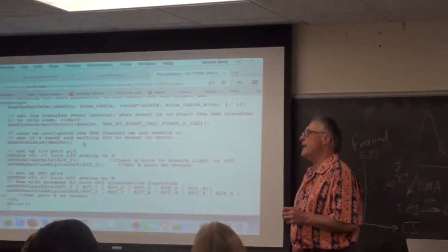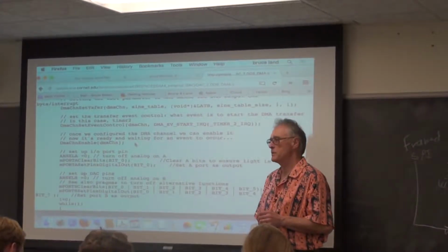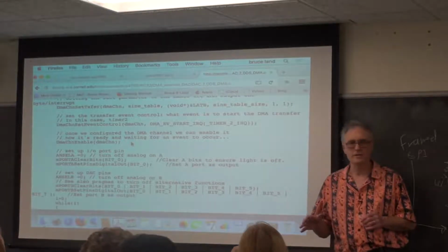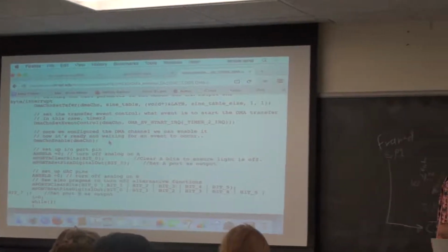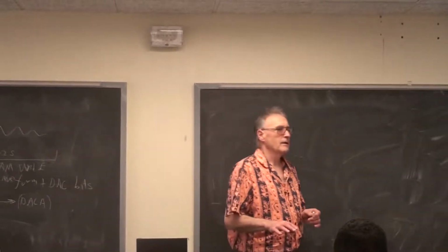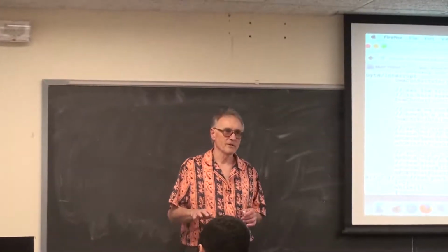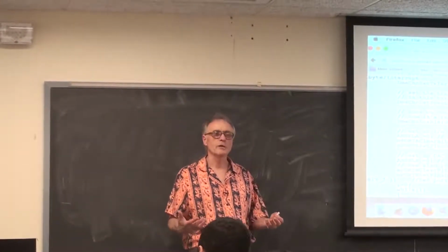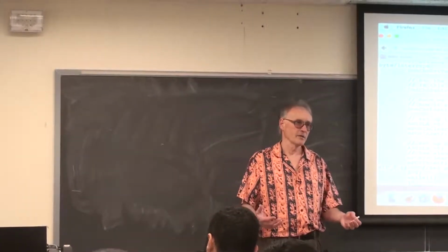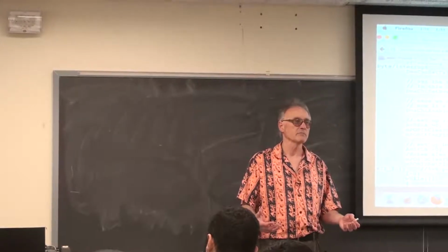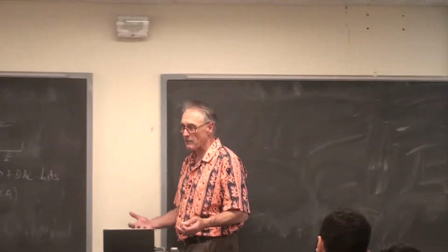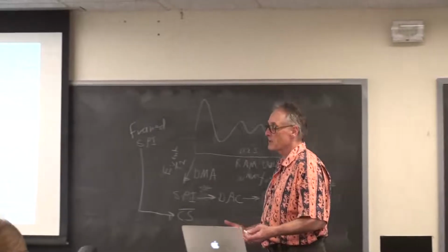You can spend days reading the hardware description of the DMA channel. I have. I think I understand what it's doing. And more days reading the plib description of how to set up the channel. But basically what you're doing is you're configuring a coprocessor by writing registers instead of instructions. And once the coprocessor is programmed by writing registers, it's going to sit there and execute.